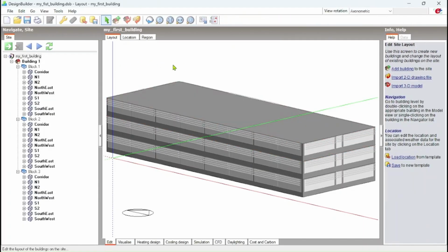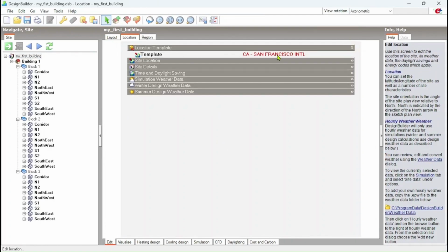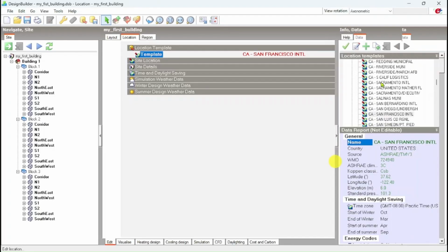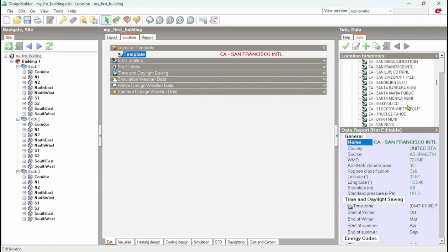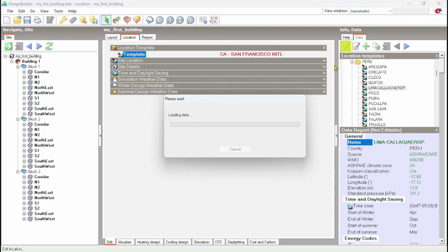And then, remember, finally, to simulate, first we have not indicated location, so we go to location, and then we select Lima as location. We have different weather files. These are typical meteorological year files. So we select this, we go to Peru, and then we have this library, and then we go to Lima. We can pick Lima, and then we can select this data.